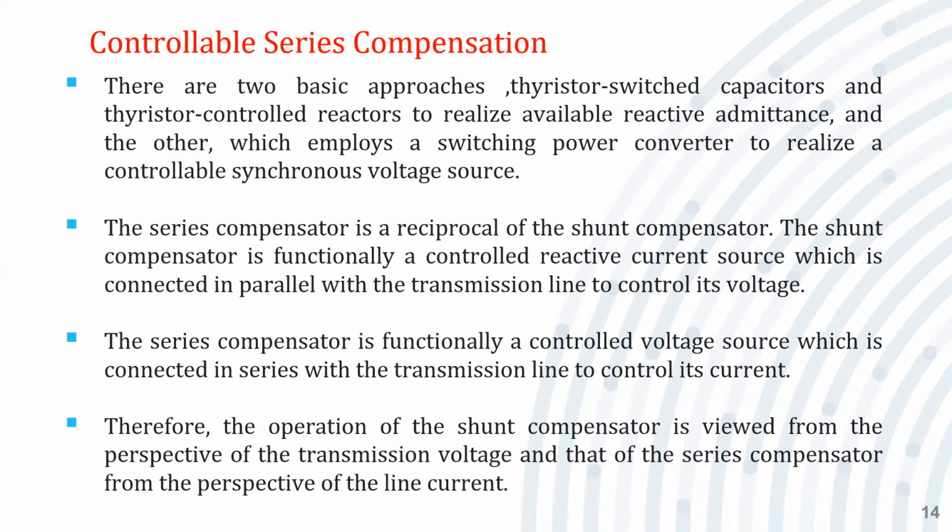Similarly, in the series compensation, the control over the compensation is going to be obtained with the help of a thyristor switched capacitor and thyristor controlled reactor to realize the variable reactive admittance.